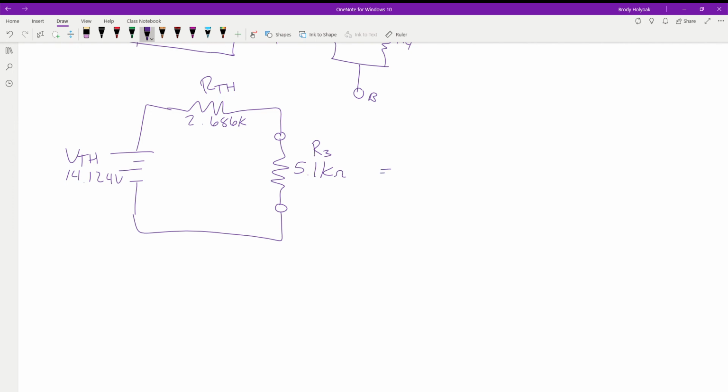So what would have happened if the voltage we had would have come out negative? How would we draw the circuit? Yeah, we would flip the battery, and we're measuring voltage from top to bottom, left to right, kind of keep that rule of thumb, same way we read. When we would get this value, it was going to give us a negative voltage because of how we're measuring with our meter.